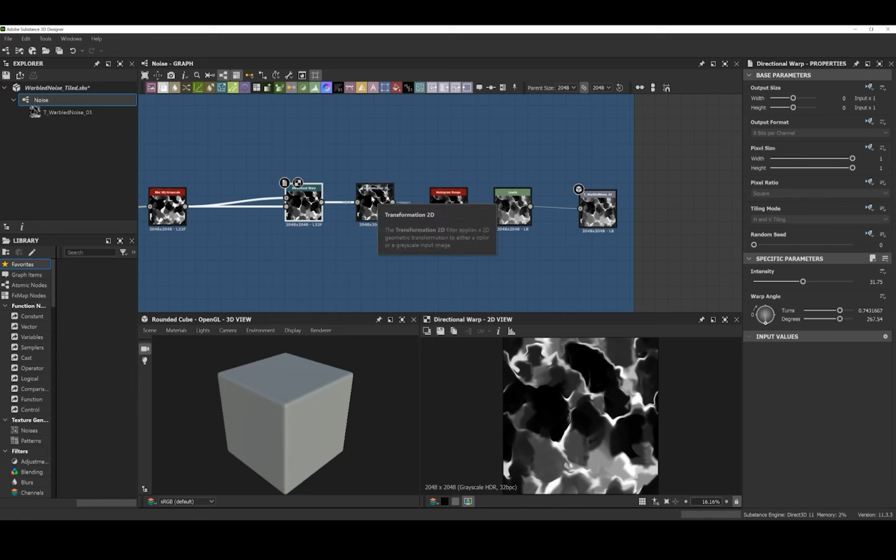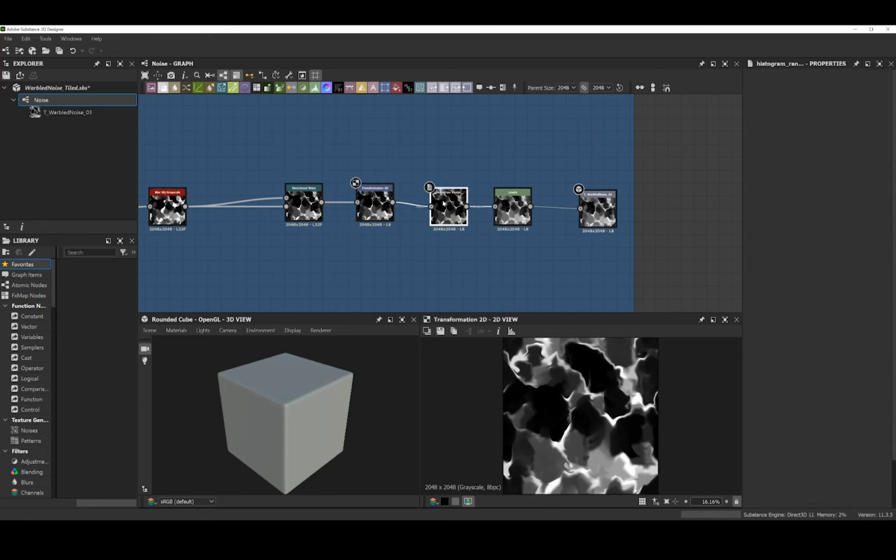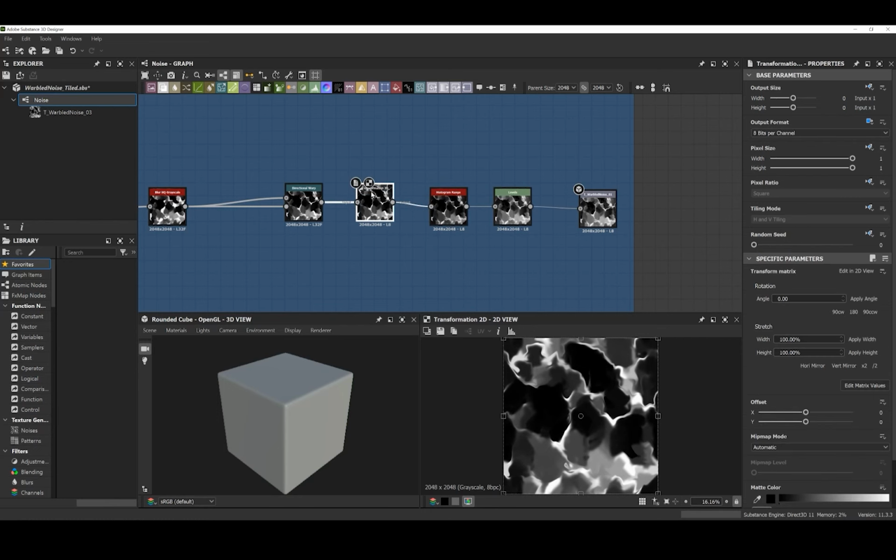And then I'm running it in here. You can do this, I think, on any node. I like to do it on just a transform node, but I'm not using this to transform anything. I'm using this to set the color output. If I were to leave this at 16, if I were to try to crunch it down to 16 bits, you can see it's at 32 floating, which is going to make this texture size very sizable. Even at 16, we're probably around 4 megabytes, which when texture memory is an issue, you want to have your textures nice and low in memory to start out.